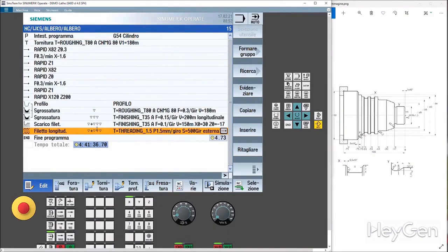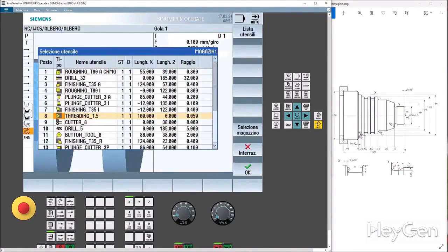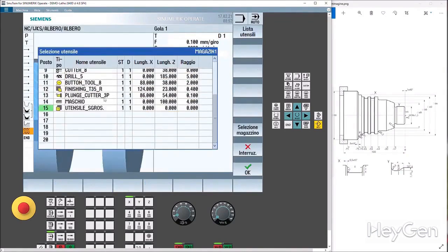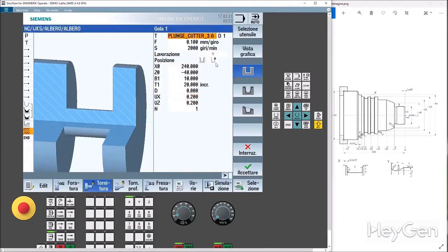Let's select the tool right away. You see, once you understand the concept, they're all the same. We have a tool for external grooves, thickness 3, and the tip radius is 2. Let's select a feed rate of 1/10 per revolution for a groove.